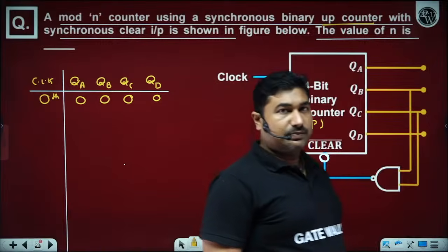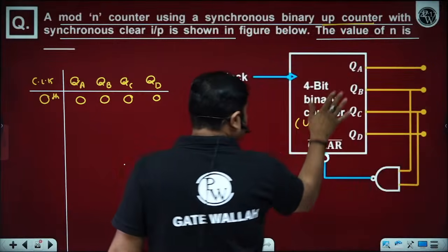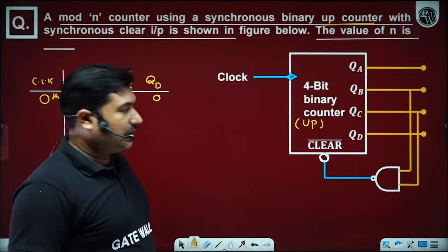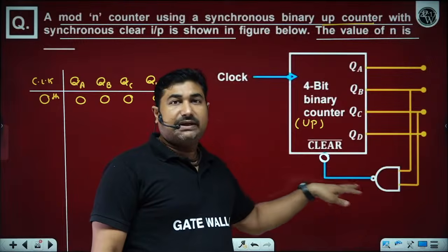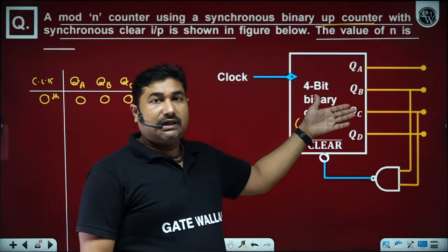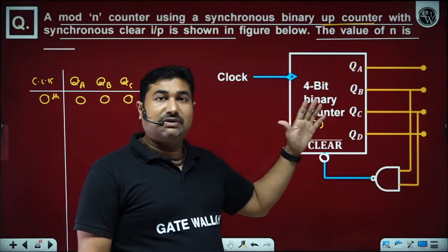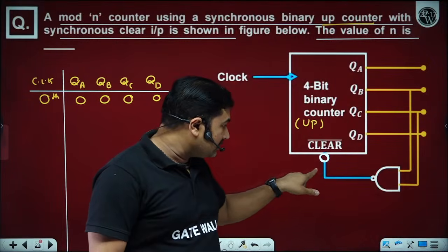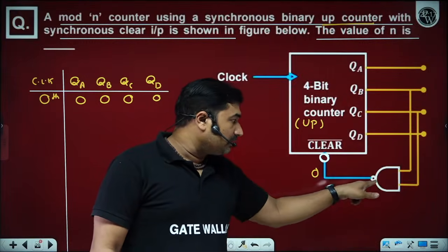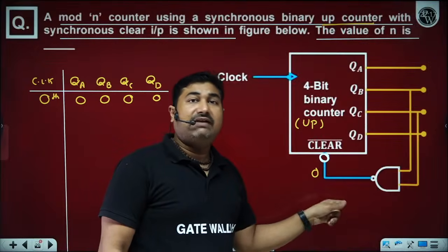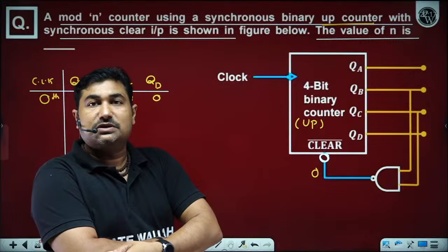Inside this circuit we have a synchronous parallel carry up counter, with each of the flip-flops connected to a clear pin. The counter gets cleared, meaning all the flip-flop states are reset to 0, if 0 appears on this pin. This pin is the output of a NAND gate, so whenever the NAND output becomes 0, the counter output will be 0 0 0 0.